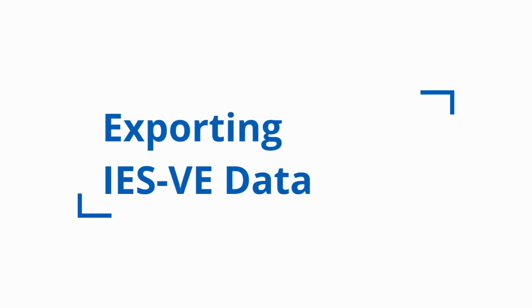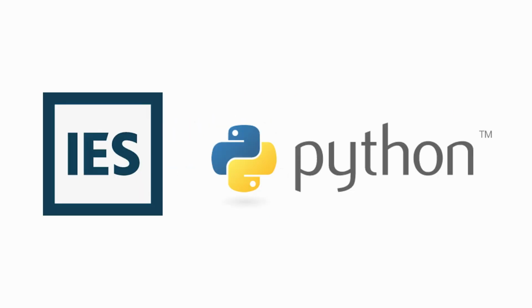In this video, we'll go over how to upload an energy model from IES-VE. IES added the Python API in VE 2017. Models created using VE 2016 or earlier will need to be updated to a more recent version, and this could involve reconfiguring some systems and rerunning the simulation.